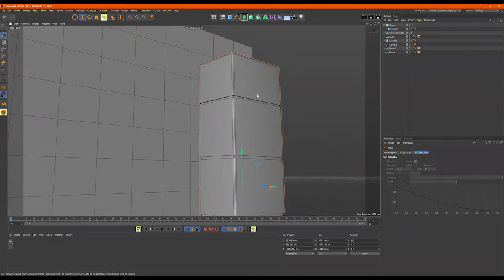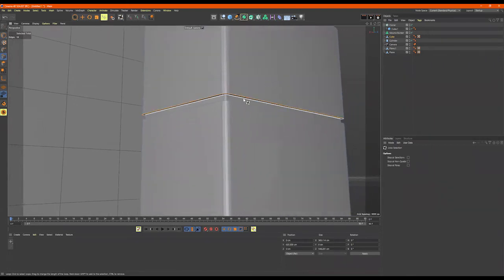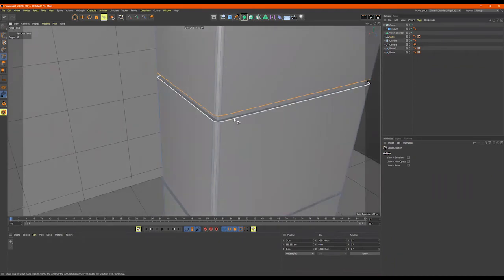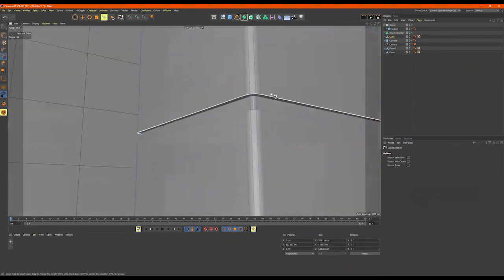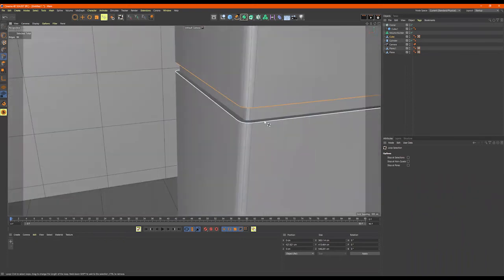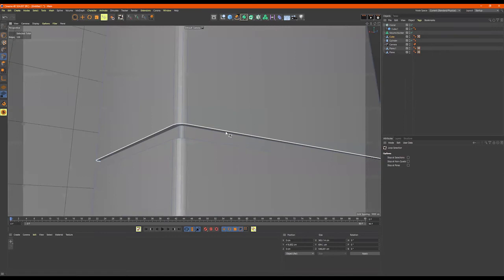And then we can do something like UL. Go to edges. And then we just bevel shift. Grab all these hard edges. So the outer, the inner. Shift, shift.